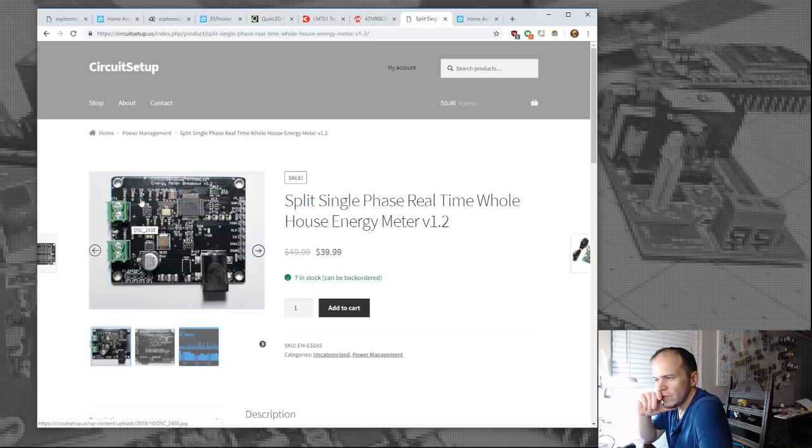When does the Wemo connect to Wi-Fi? Okay, inside the load center. Well, what I have actually is, because of the wires on those split cores, I didn't want to mix low voltage stuff and mixed voltages in there inside the breaker panel. So I just put the clamps inside the breaker panel, and mine had enough room for those little wires from the clamp, and I just put the cover back on. They come out the side.